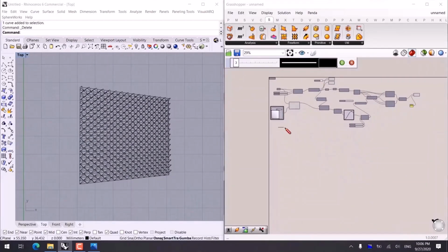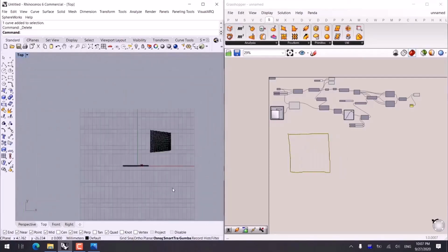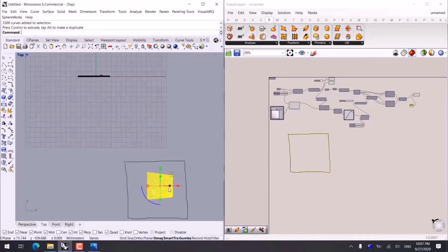Then I want to have this in Grasshopper. For example, I want to have the 2D drawings in a region. Firstly, we specify the frame or the region that we want to have the 2D drawing inside, and then OK, like this. Then we select the curve, right click, then we click on Set Multiple Curves, Rhino. Then we will have the drawings in Rhino, as you can see.